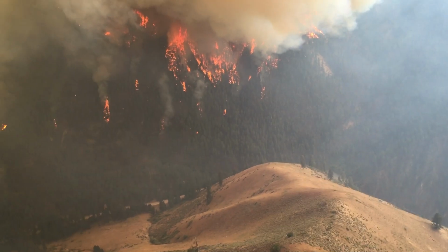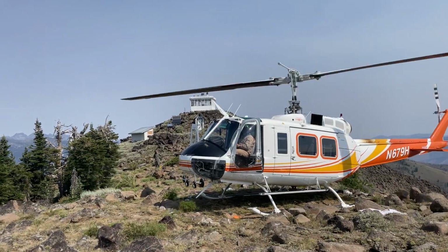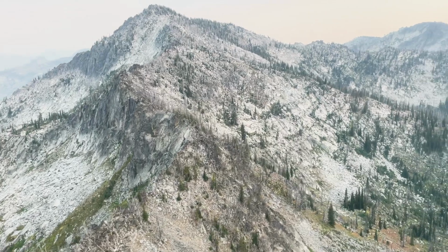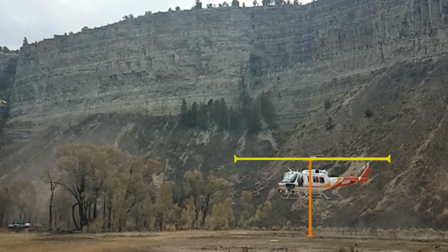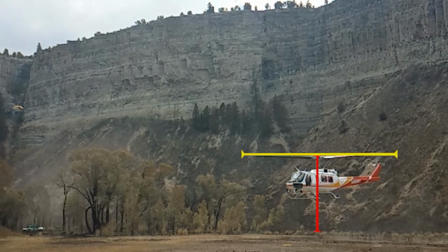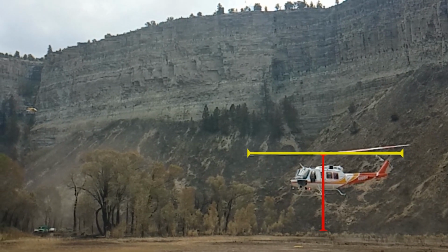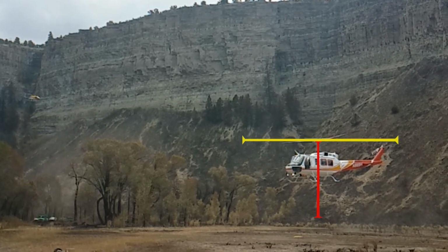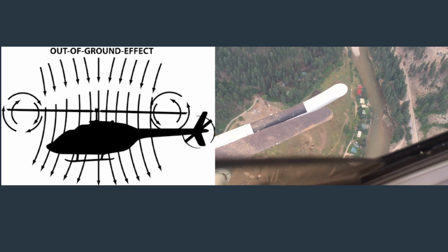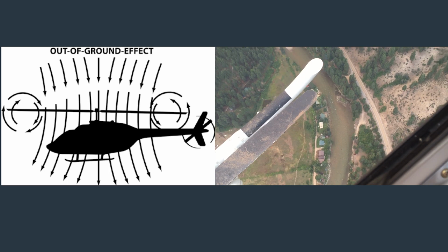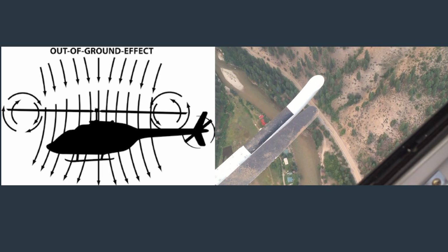Rough terrain, long grass, ridge tops, or pinnacles may reduce or even eliminate the advantages of ground effect. Once the helicopter exceeds the 1/2 rotor diameter distance above the ground, the cushion of air dissipates and is now hovering out of ground effect, or HOGE. To maintain a hover, the helicopter must now use considerably more power, reducing its effective payload.